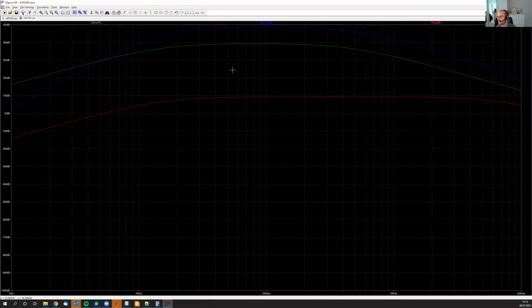So basically the idea is that those are the values you would get individually if you give the input signal to each stage. And then this Vout bandpass total is the two-stage filtering, first Vout 1 and then fed into Vout 2. And this is the result of both of them if you have them sequentially.